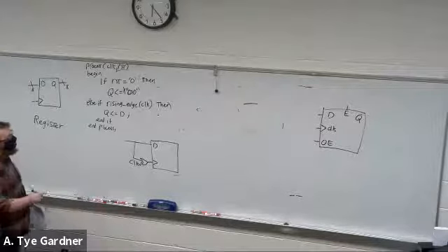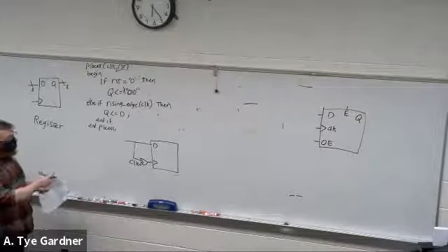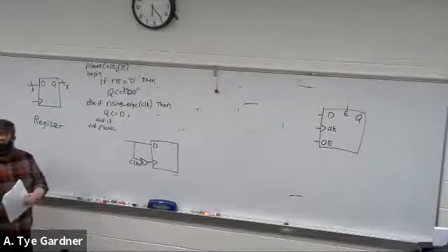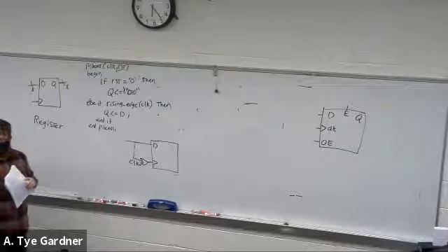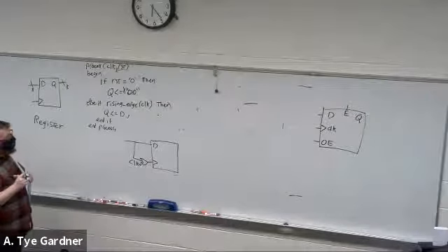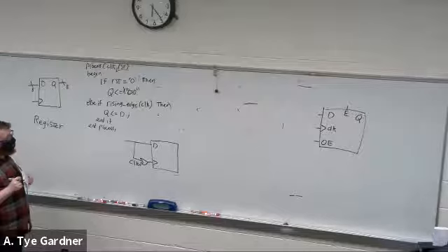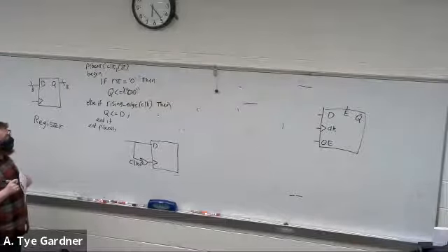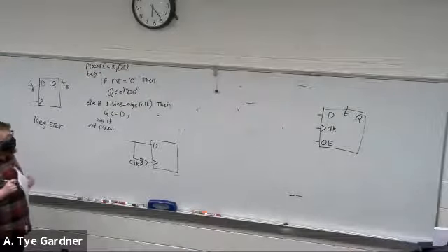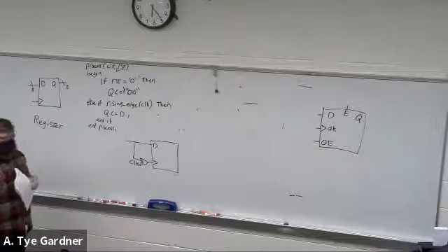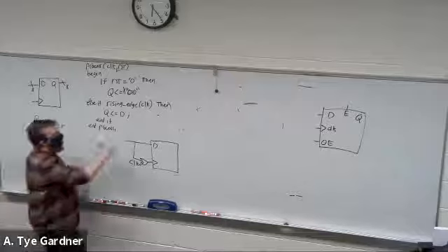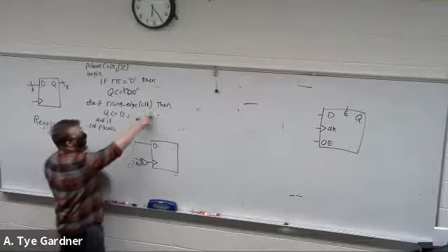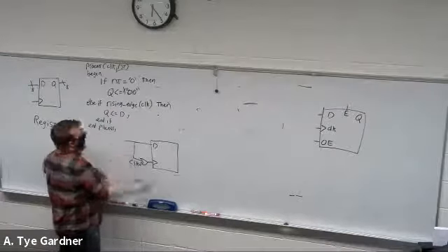If I wanted to add an enable, where's a good spot to do it? Because you brought it up. Maybe, yeah, so we'd want to add the and to the rising edge of the clock. Yes, so you could add if rising edge of clock and enable.